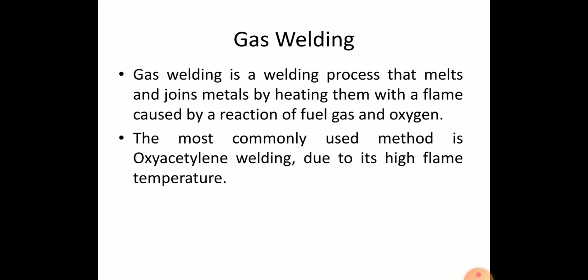Gas welding, also called oxy-fuel gas welding, uses the heat from the combustion of a fuel gas such as acetylene in combination with oxygen. The process is a fusion welding process wherein the joint is completely melted to obtain the fusion. The fuel gas generally used is acetylene because of the high temperature generated in the flame. This process is called oxyacetylene welding.